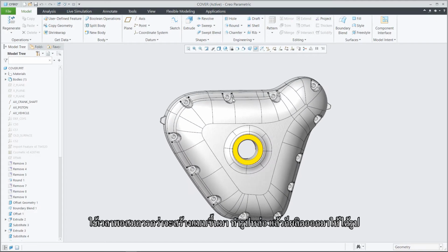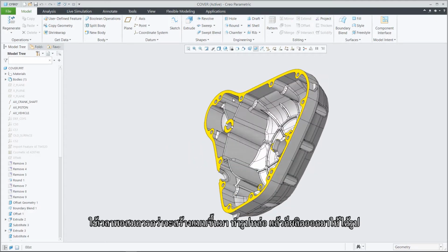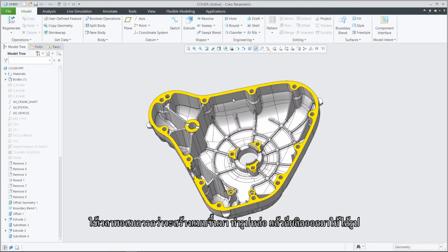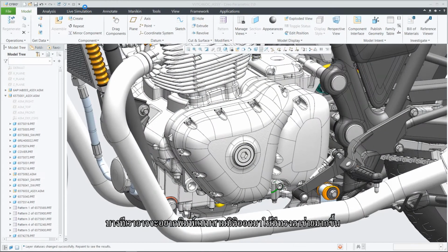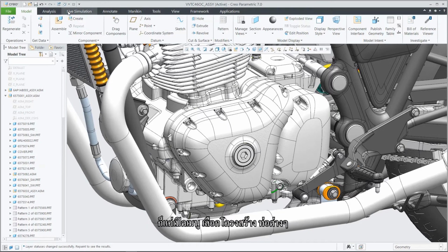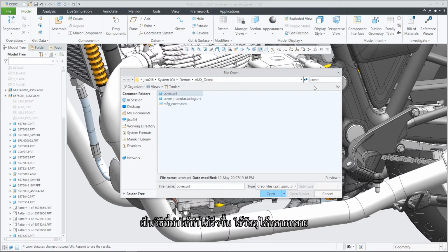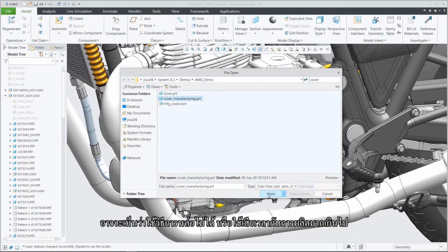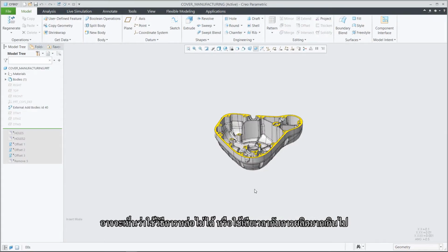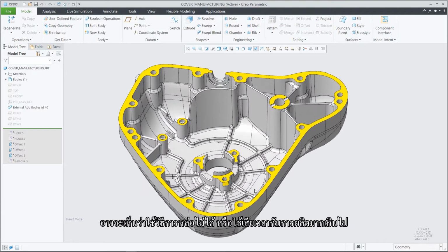It takes a lot of time to machine it, or to make castings and then machine it down to shape. But maybe we want to 3D print it, more of a net shape where we just go in and machine bosses and holes and so forth. Maybe that's going to be a much faster way, allow me to use some different materials, maybe that don't do well with castings and so forth, or really cut down on that machining time.